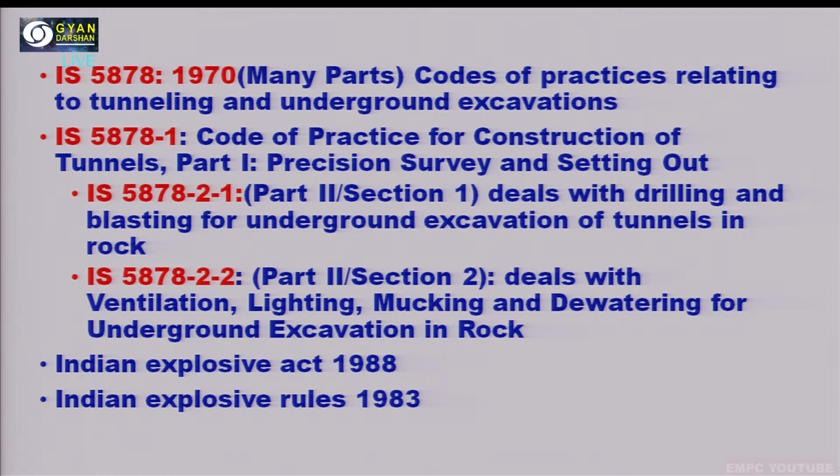Because during the tunneling, there may be water inrush or water ingress, as I told you earlier, or some water table may be there. So we have to dewater. We have to remove water from that place basically, so that we can make progress in our excavation work. So such type of guidelines are there in this code.